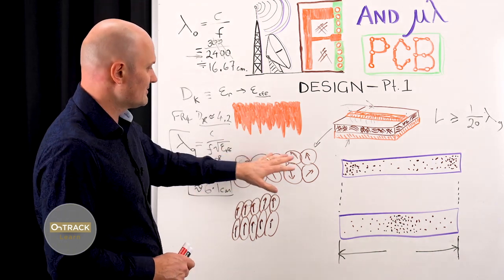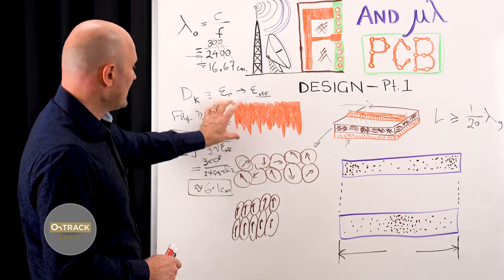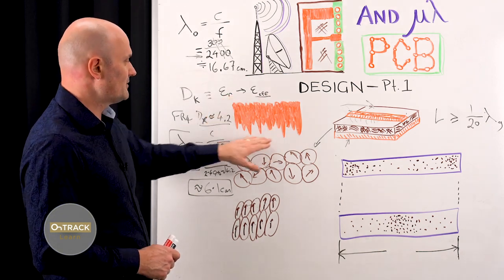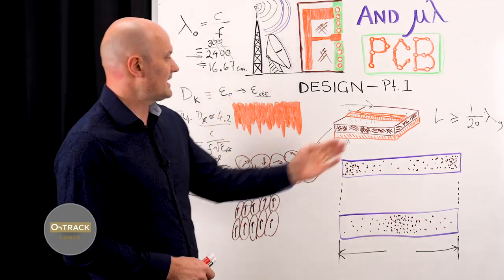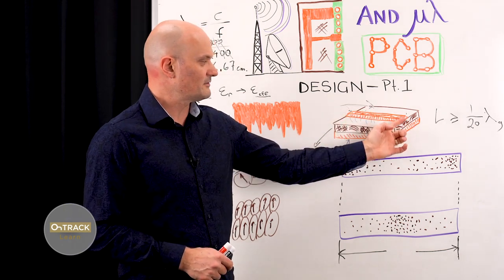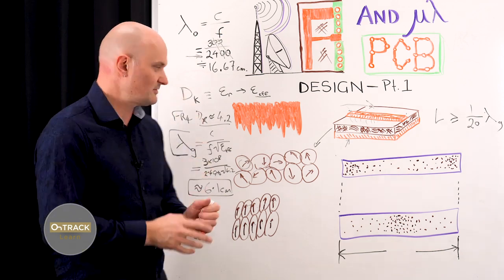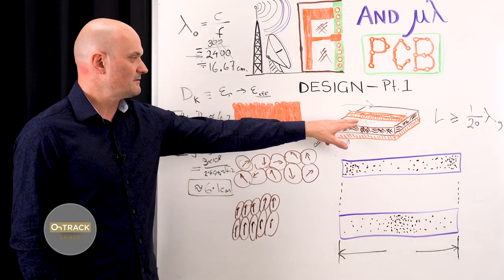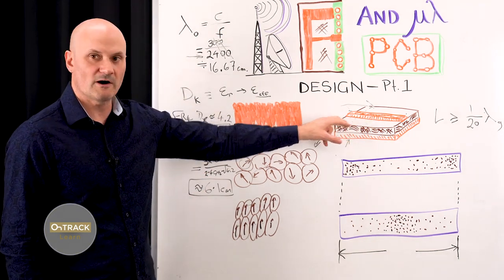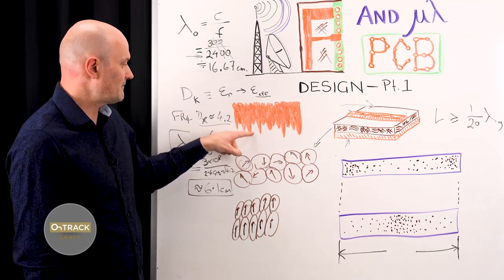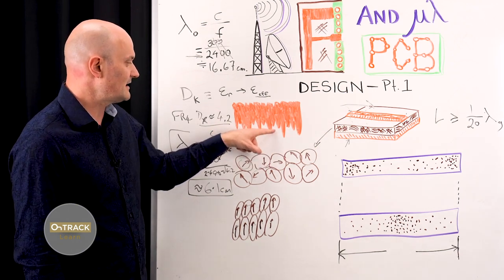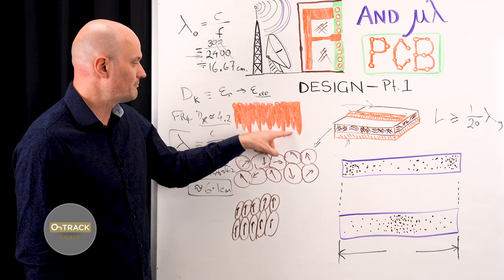Okay, so we've talked about insulation material, guide wavelength, all of that. Let's talk about conductors a tiny bit. Here I have a cross-sectional view I've drawn. If you get a section of a small PCB trace and you look at it under a microscope and it's polished, you'll see the surface of typical PCB copper is very rough. It's actually intentionally made this way.